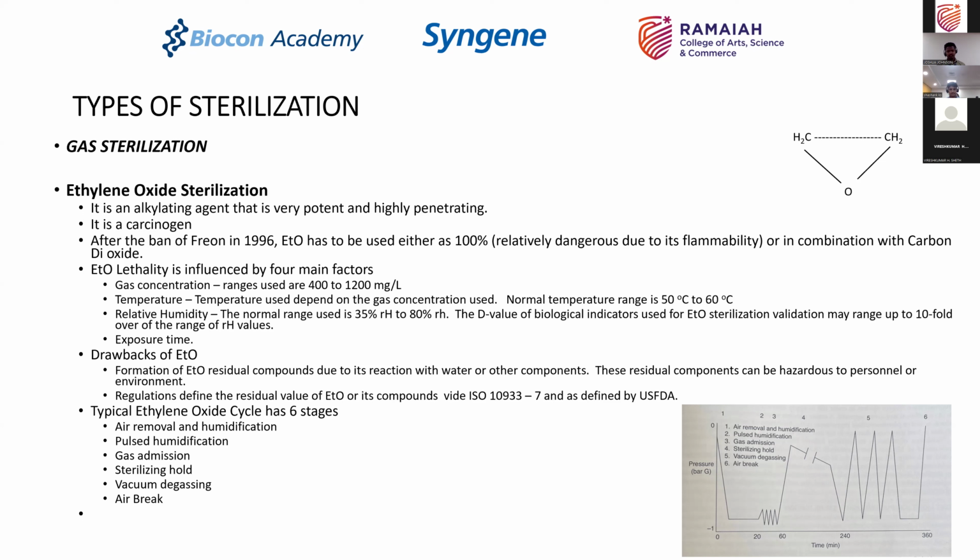After you've brought it to 55%, you hold it for a very short time, and you will then see that the humidity is fluctuating. So you again introduce a spray of water so that it goes back to 55% or slightly above. That is the technique used in this phase where you achieve the humidity. You will humidify it, then you will see a drop, you will rehumidify it and see a drop, you will rehumidify it and see a drop, and you will try and get there to a stage where you are ready to introduce the ethylene oxide and carbon dioxide.